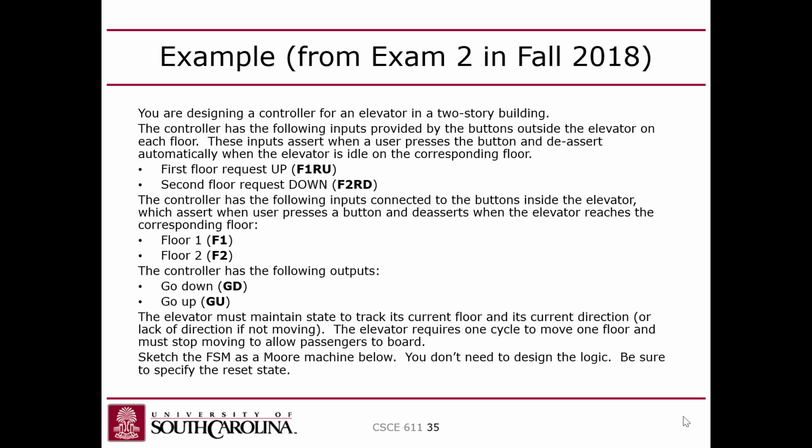This may be a little tedious in the state machine, but if you're on the first floor and you hit the F1, then it'll loop back into itself. Yeah, that's implied. When you design the next state table, when you have to fully enumerate every combination of things, then yes, you would actually have to stay in that state. So the loopbacks are usually implied. If you don't draw an arc, like if you don't satisfy any of the conditions of an outgoing transition, then the assumption is you're going to stay in that state.